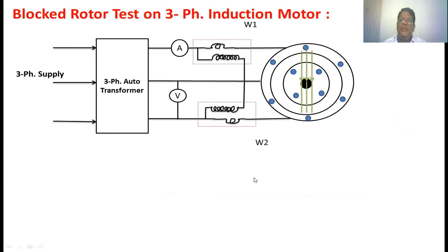Block rotor test on a three-phase induction motor. The name itself says it: the block rotor test. We are blocking the rotor. Whenever we block the rotor, the induction motor behaves as a transformer whose secondary winding is short circuited.